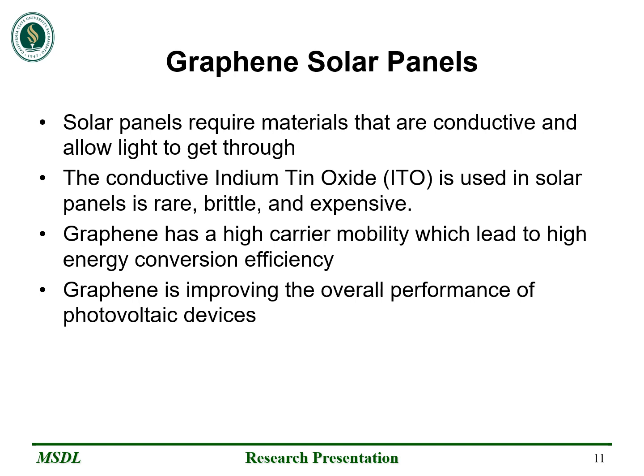Secondly, graphene has a unique ability to maintain hot carriers at room temperature. This is due to the fact that graphene has a linear electronic dispersion relation near its Fermi level, which allows for the creation of a large number of hot carriers that can be maintained in a highly excited state. Finally, graphene has a high surface area and it is transparent, which allows a large amount of light to be absorbed and more charge carriers to be generated. Graphene can be used to improve the overall efficiency of photovoltaic devices.